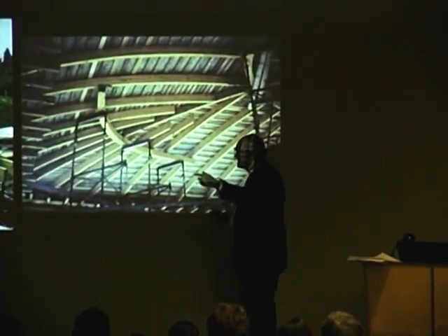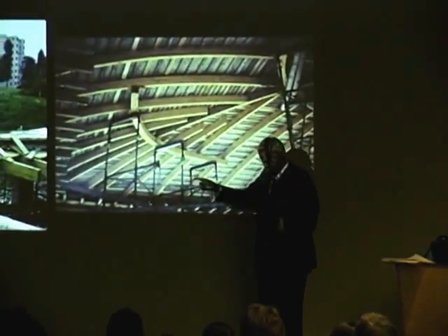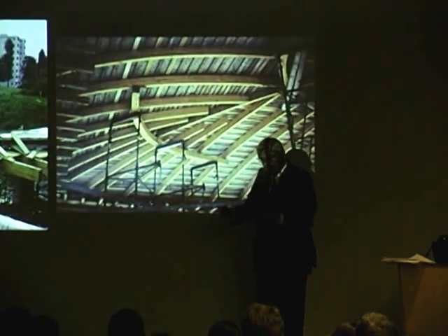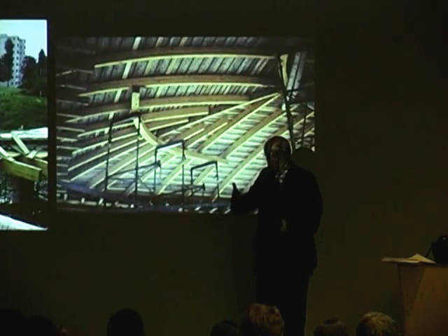That means now what he's doing is, as we will see, he is designing a concrete system with such a form that there is no tension stress in it due to its own load. And then he is putting the insulation there so that through the concrete thickness, the concrete will have only the heat of the outdoors. So it'll have no thermal gradients. So there is no way that concrete will crack. Since it won't crack, it means it won't leak.